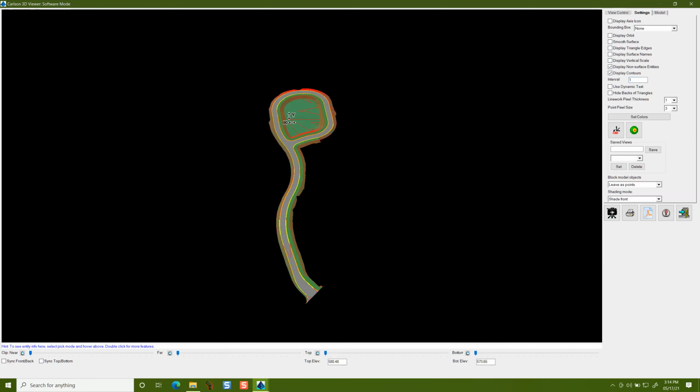But I mean the road loops. There's a contour across the road, but that road is pretty flat. These are 1 foot contours, right? And you got these little things here, and you get into the road, and there's one contour there, and that does not vary by a foot all the way around. It should. It's not following something. The road's a little bit too flat. I know it's a flat road, but the profile goes in at least a 0.5%, and over that length, I should see a couple different contours.